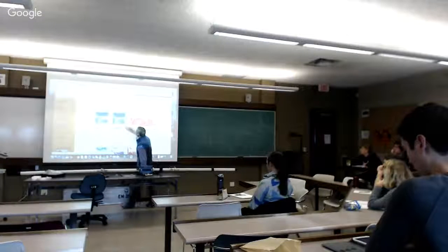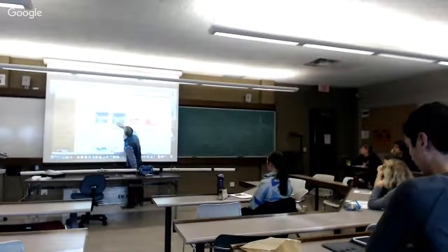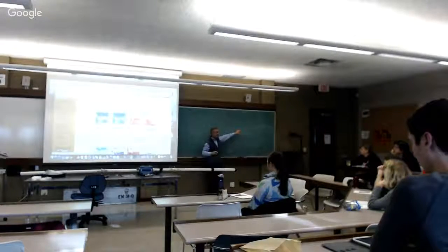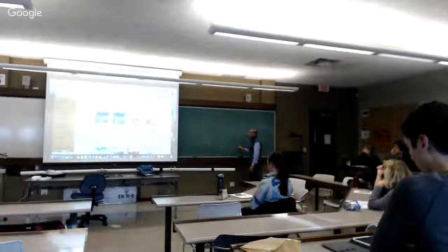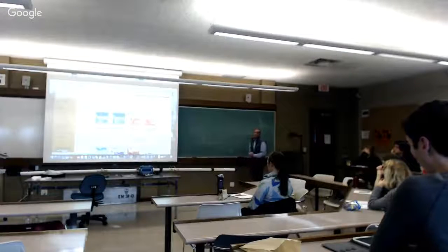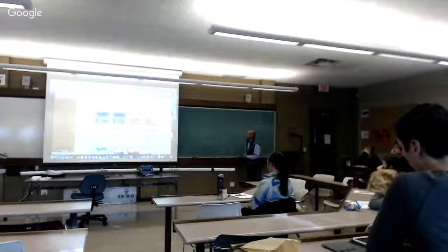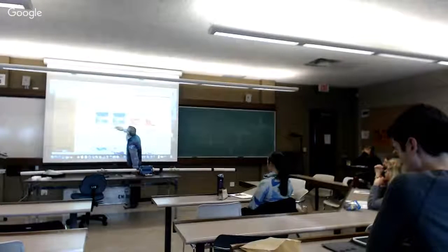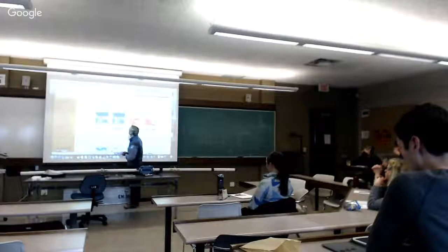The same is true over here. You can see again there's a positive, and then there's a negative and a positive. So that kind of characteristic signature is actually seen right in here. And because you understand how this EM31 works, you might think, oh, no, there's something there that is worth investigating. So just by simply looking at the signatures and the patterns, you get the idea that there might be some kind of a conductor that's coming up through here, and maybe something through there.